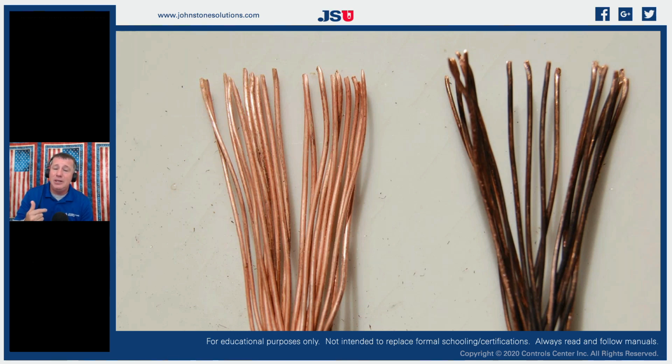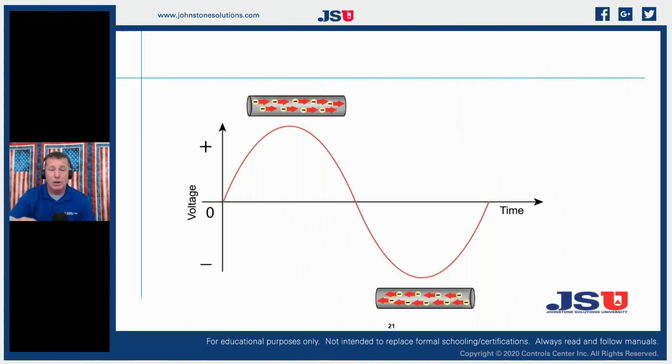That's why we like using stranded wires on communicating systems. Those stranded wires just give us more paths to be able to communicate on. So a lot of times, when we install new communicating systems, we need to pull new control wire as well. Sometimes that old solid conductor works fine, but typically it only works fine if there's no breaks in it anywhere along the path.